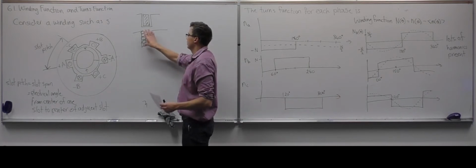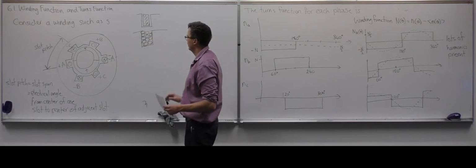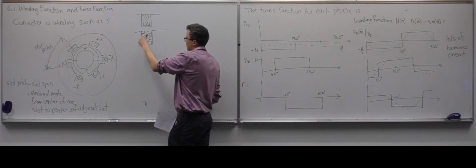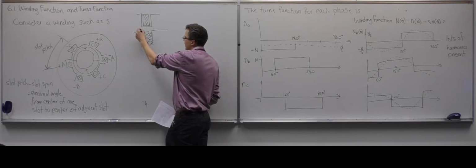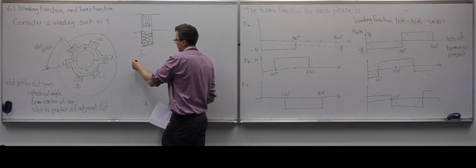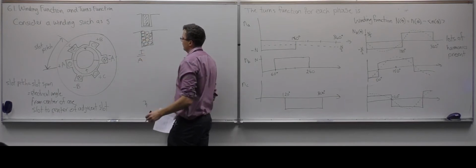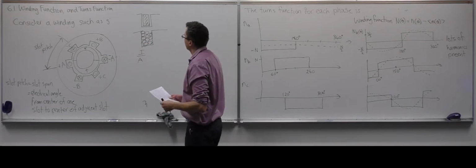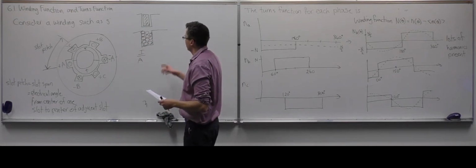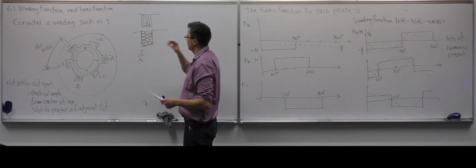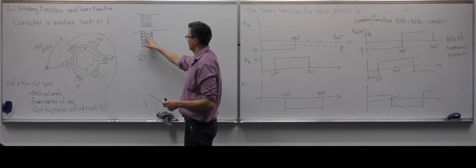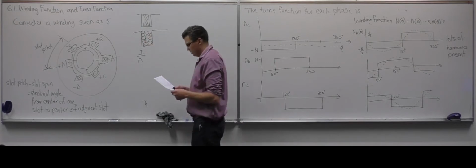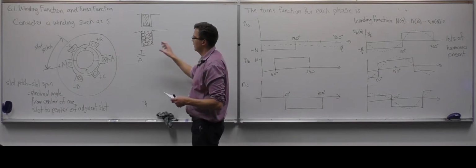You have to assume it's not all conductor, so the current density, the current over the area of the slot, needs to account for the fill factor. Those things need to be looked at when modeling. You don't usually model all of the conductors individually because that would result in an extremely long simulation, and it doesn't add that much to the model.